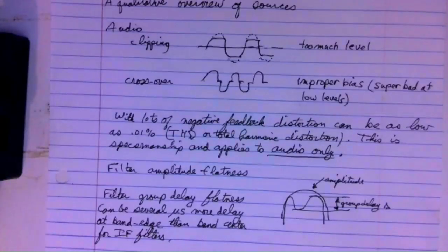It doesn't really buy you anything, and in fact, it may actually not be good for real world distortion from like large input levels. This negative feedback can cause waveform distortion when you overdrive it, and it can be worse than the clipping. And it's just a specsmanship issue, and it applies to the audio only, not to the FM receiver part.